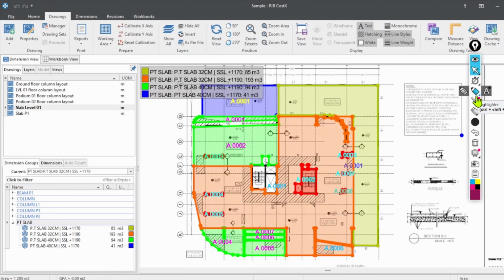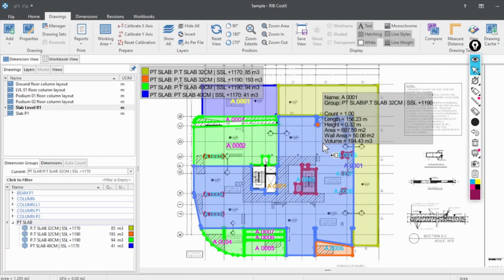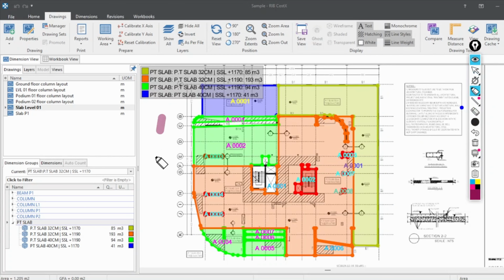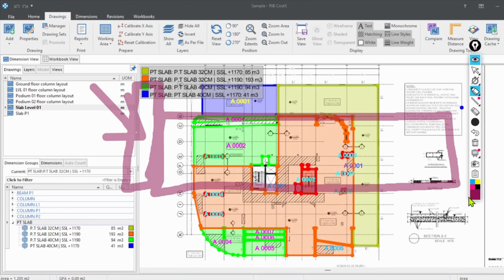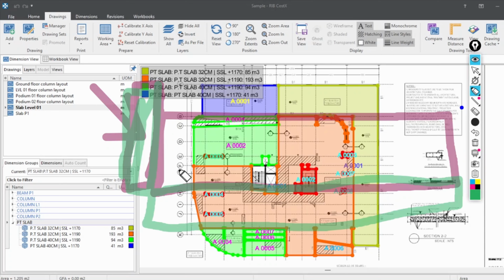The slab has two types of shuttering: the soffit of the slab and the side of the slab. Imagine this is a slab. So these are the sides of the slab. Here also we need to provide formwork. For the soffit also formwork needs to be provided, right?